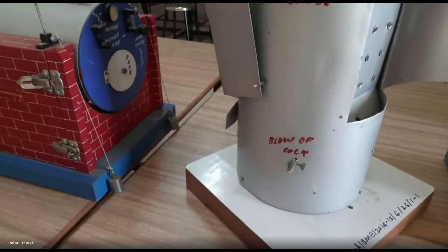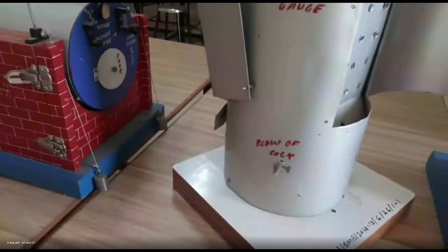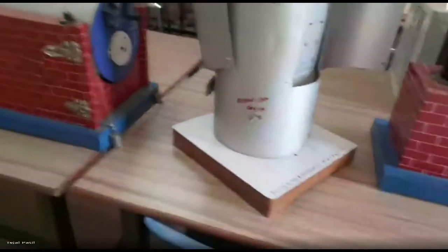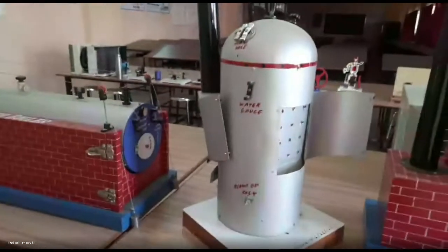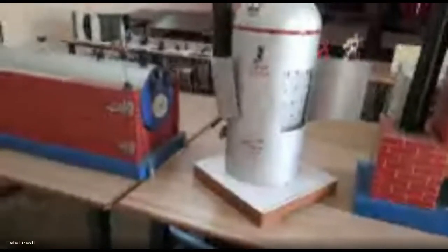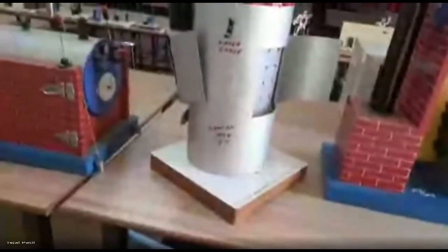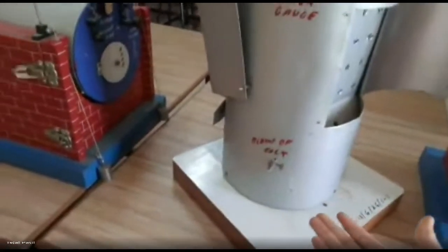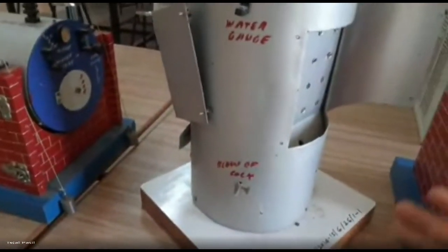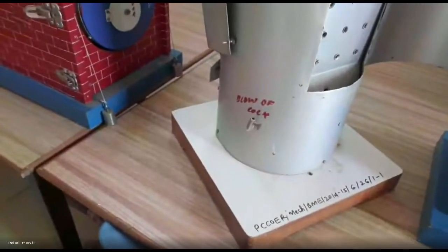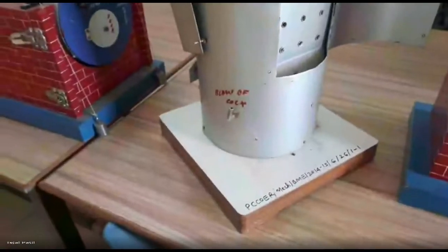See what happens: a boiler contains water. It is not possible that whatever water you are sending into the boiler will be in the purest form. So definitely it will contain some amount of mud. That mud will be collected at the base of the boiler, but timely you need to throw it out of the boiler. Otherwise, what will happen? The boiler performance will reduce.